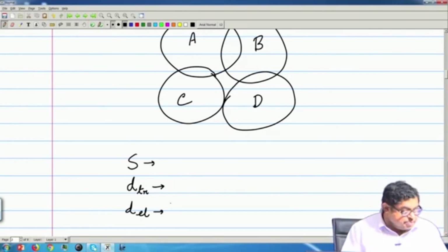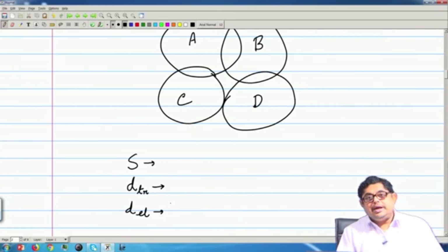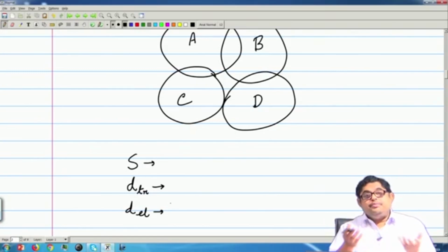So, that is the main thing, and if we take this ratio, we have seen that it is beneficial for the angle detection, because that ratio gives directly the linear variation with angle. Also, we will see later that that ratio is invariant to the drift. Initially, when the monopulse was introduced, people did not understand, but later they found out that the ratio is invariant to drift.